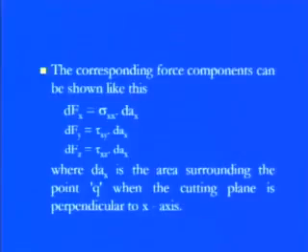Okay, so now you see here, as far as the force component in the x direction is concerned, we have dFx is sigma xx. That means in the x direction we have normal stress because of the perpendicular axis, but the other two force components, dFy and dFz, are not perpendicular to the area concerned. So here the normal stress components are not being set up within the object or outside of the object, that means the surrounding part.